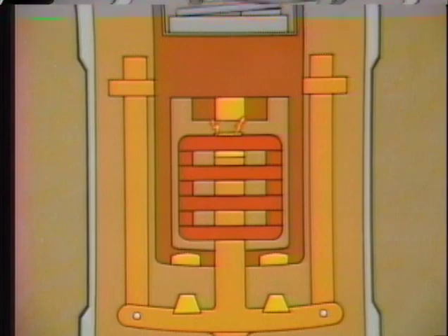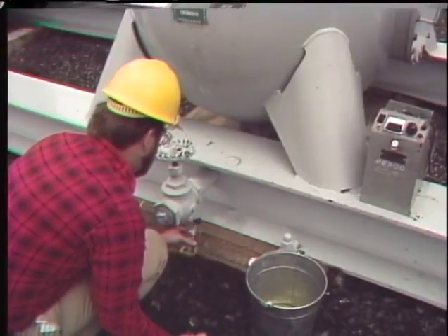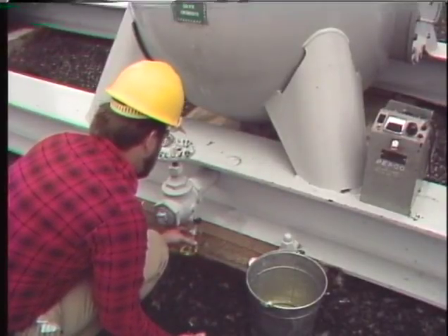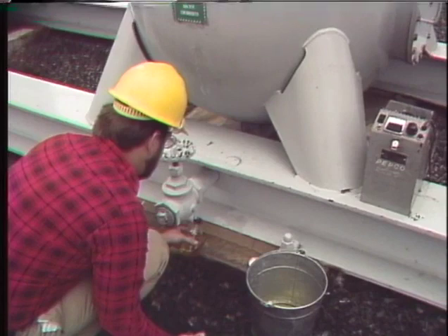The oil in a circuit breaker insulates the breaker's arc interrupting mechanisms and helps to extinguish arcs by inhibiting the flow of current across open contacts. But over time, the dielectric strength of the oil, its ability to inhibit current flow, decreases due to moisture, carbon from arcing, and other contaminants. So the dielectric strength of the oil is checked periodically.